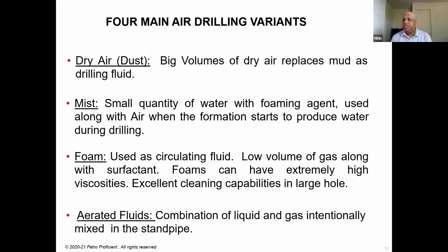When you start to see that the formations have started to produce water, now you're drilling underbalance, and if you pass through any water producing zones, that water needs to be displaced out of the well. It is done by adding some foaming agent and water to your air. This technique is called mist drilling.